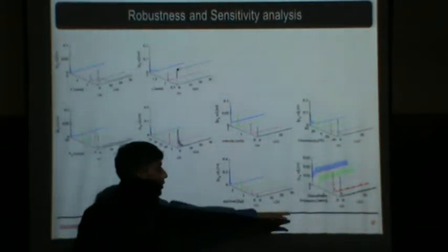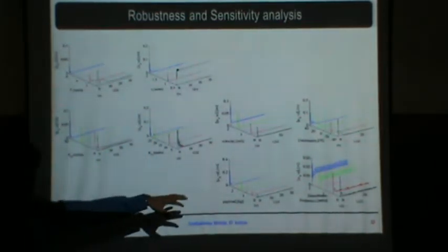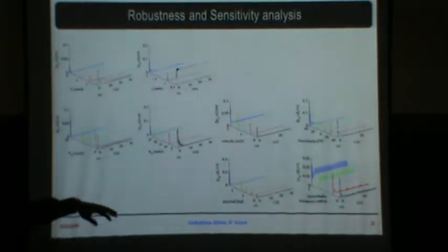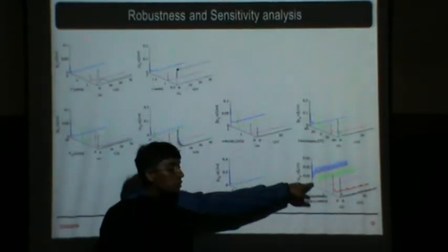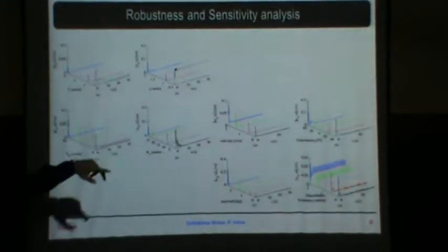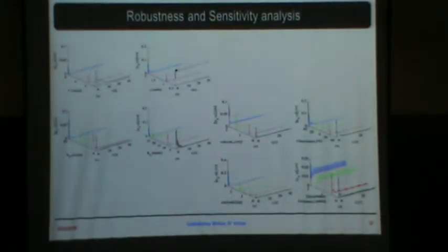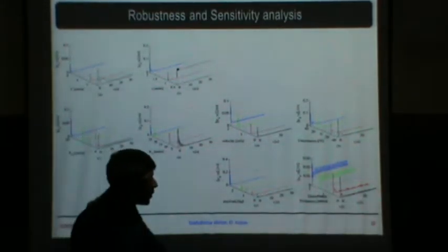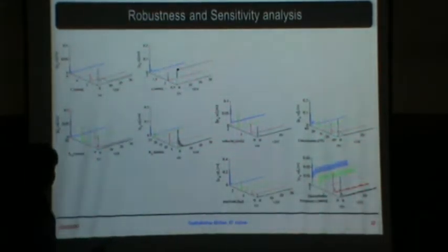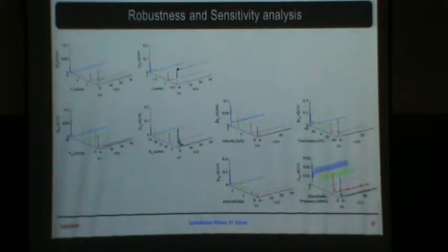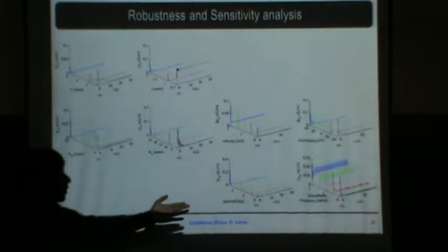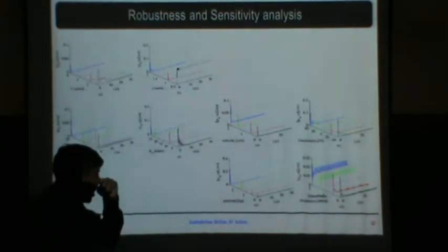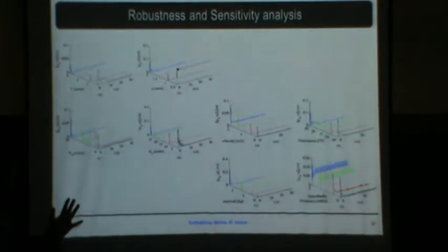Like we have checked the disturbance frequency. Initially we assume that the disturbance is slowly varying, but we try to vary the frequency. While we are varying the frequency, we can see that the controller is not able to overcome it. So it can only handle a certain level of fast varying disturbance. For example, if you have a system and you are continuously oscillating it, the system cannot cope. That's what it is showing here. And this is an unrealistic situation.